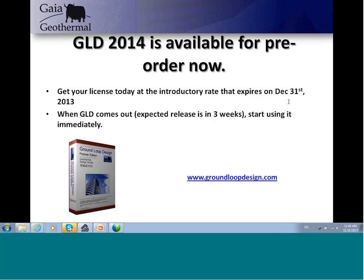When you're doing a monthly simulation, we're using 48 data points, so we use a lot more data. In addition, it's a different heat transfer model, sort of a numeric model versus an analytic model. For those two reasons, the model and the amount of data, we get different results. The challenge for designers is to understand the difference between those two results and come to a design they're comfortable with. We spend a lot of time in our online training explaining recommended processes for doing that.